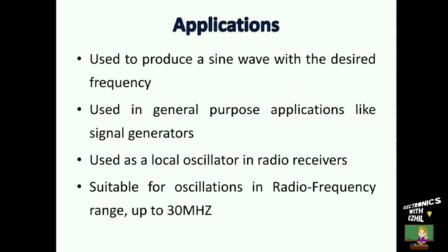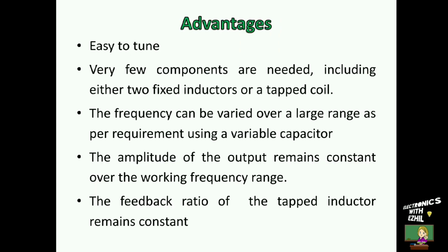Applications. Hartley oscillators are used to produce a sine wave with the desired frequency. They are used in general purpose applications like signal generators. They are also used as a local oscillator in radio receivers. They are suitable for oscillations in radio frequency range up to 30 MHz.